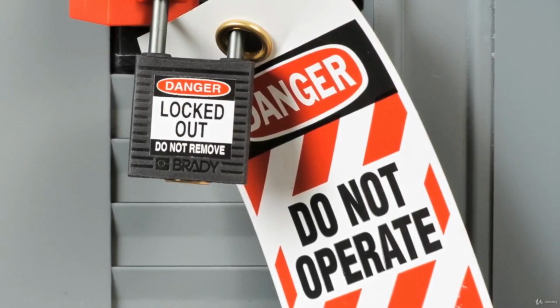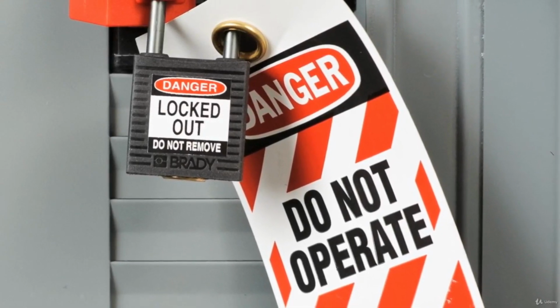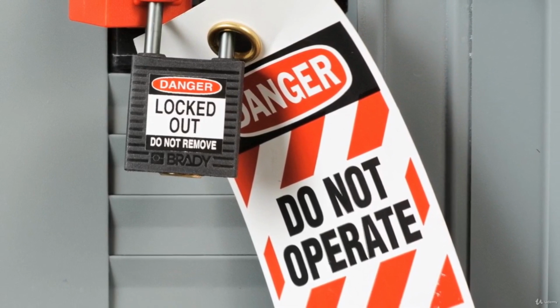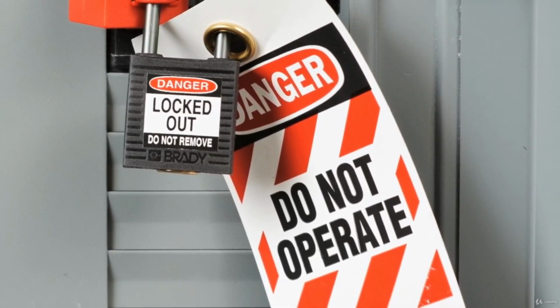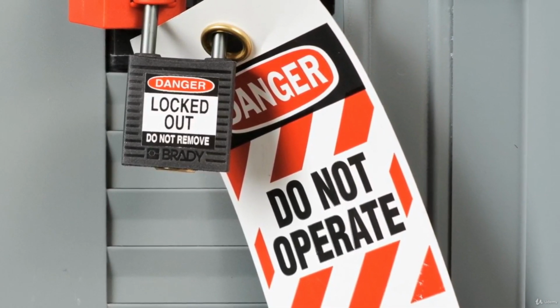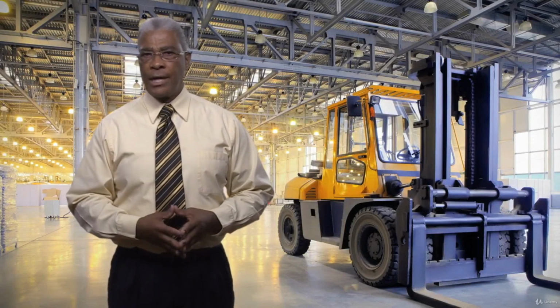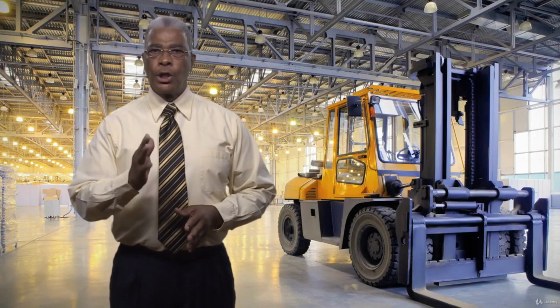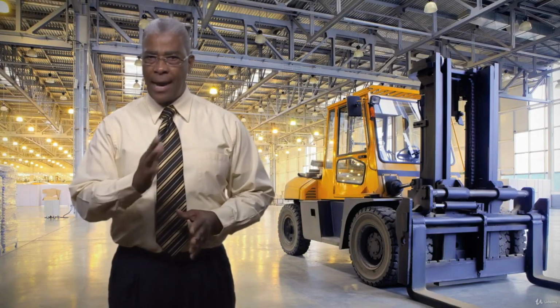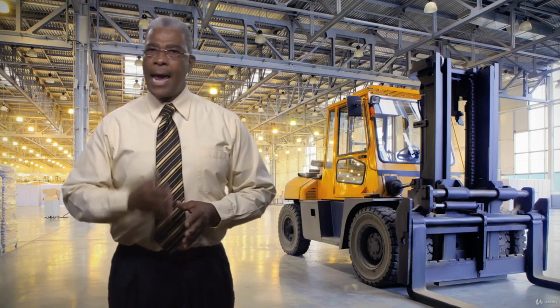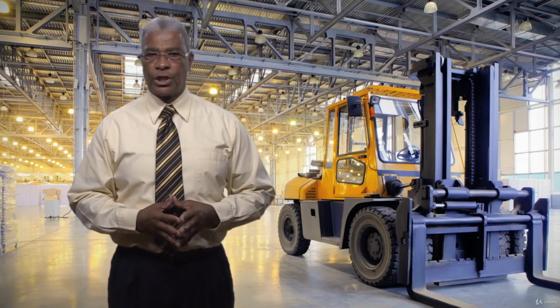Lockout is the preferred method of isolating machines or equipment from energy sources. All equipment must be locked out or tagged out to protect against accidental or involuntary operation when such operation could cause injury to personnel. Do not attempt to operate any switch, valve, or other energy isolating device when it is locked or tagged out. Use a tagout system only if an isolating device cannot be locked out, or there is demonstration that a tagout system provides full employee protection.